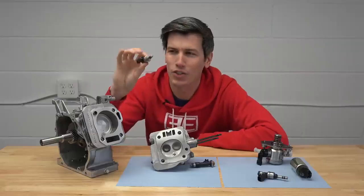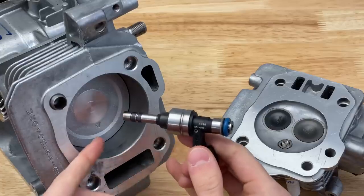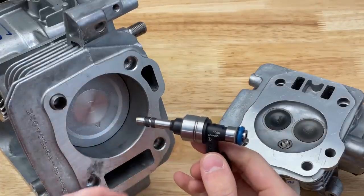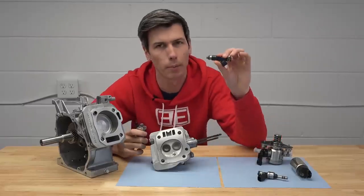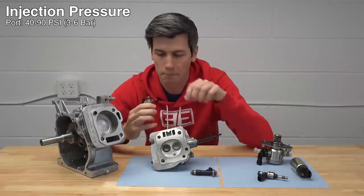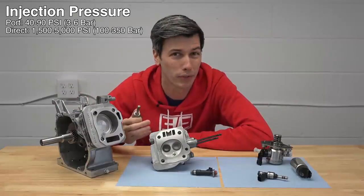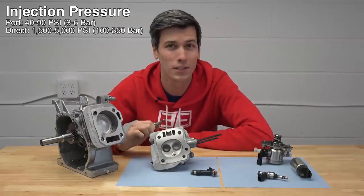So finally, we get to direct injection, and as the name implies, these spray fuel directly into your engine cylinders. Now, where a port injector may spray that fuel into the ports at maybe 40 to 90 psi, direct injection used in gasoline engines will spray in the fuel at 1500 to 5000 psi.